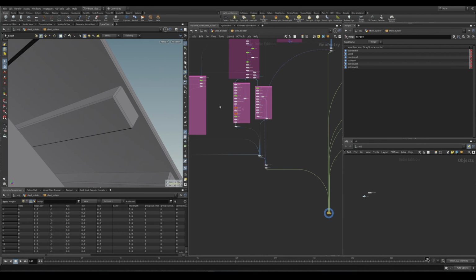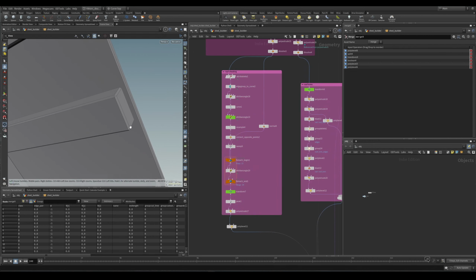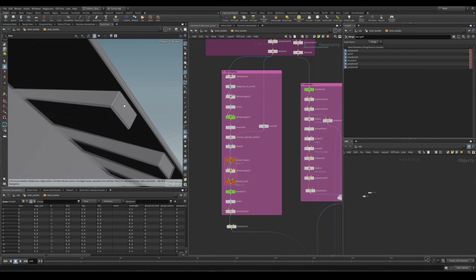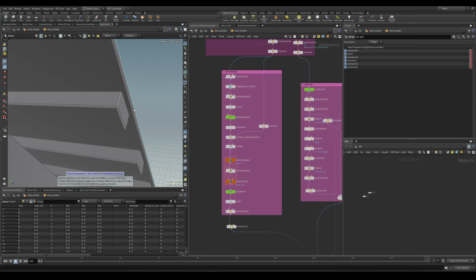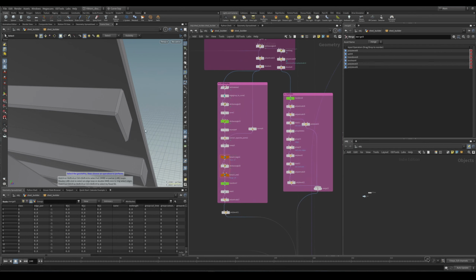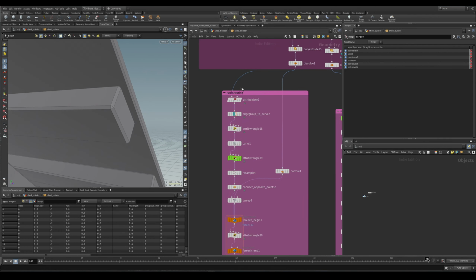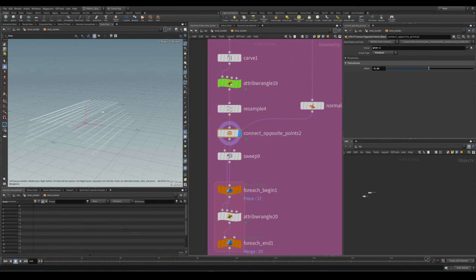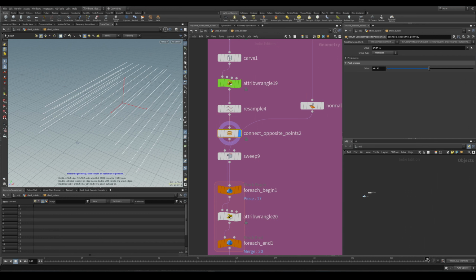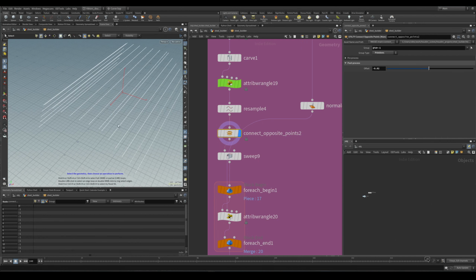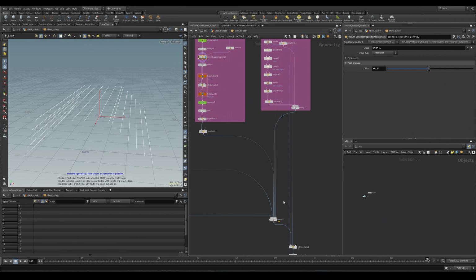By default, our roof shedding was exactly the same length as our roof, which is not actually realistic, because usually the roof is a little bit longer, with the roof overhanging the wood pieces. So for the gable side, what you can do is go to the roof shedding part, where we basically created our board from connect opposite side. And if you remember, we also created our post process option to make our polylines longer or shorter. So just subtract like 2 centimeters from it, and that's how we get our overhang on the gable side.